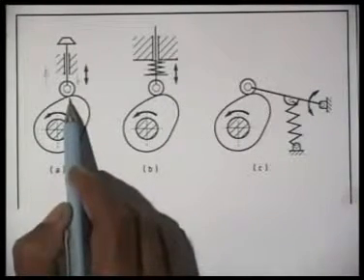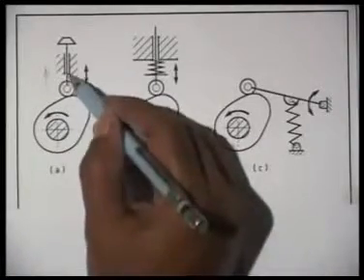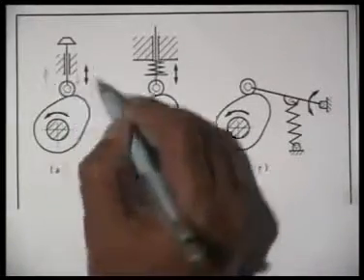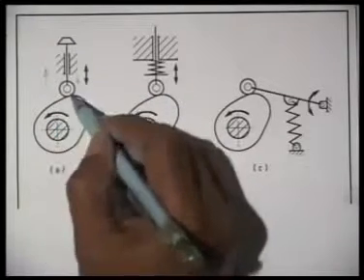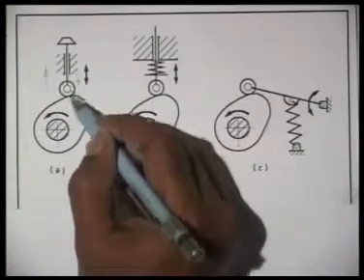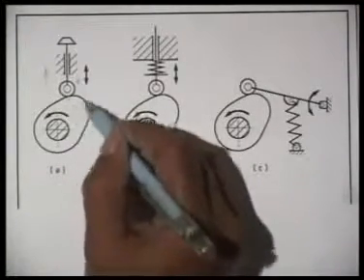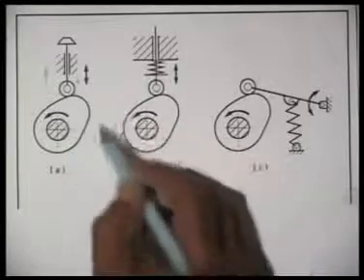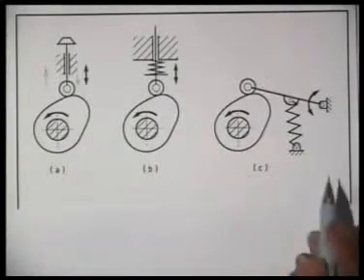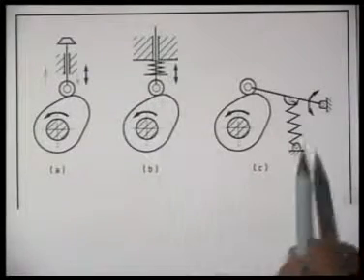In the absence of the spring, if we leave it only to gravity, the maximum acceleration can be g in the downward direction. But if we want the follower to have higher than g acceleration, then there will be loss of contact. The cam will rotate, but the follower will not follow the cam profile. To ensure the contact during the entire stroke of motion, we use this spring.